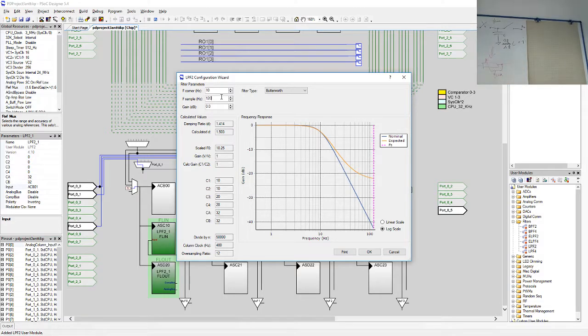Okay, so I have a cutoff frequency at 10 hertz, which means that at 50 hertz I have 20 dB of attenuation, and that 50 hertz would be roughly my Nyquist frequency for this system. Remember, from digital signal processing, in order to prevent aliasing, you need to do it like that. Right? Maybe.